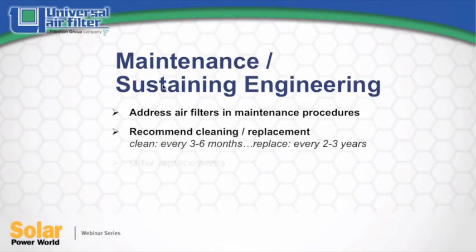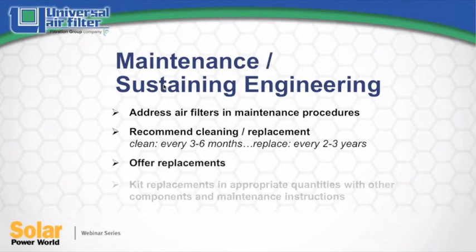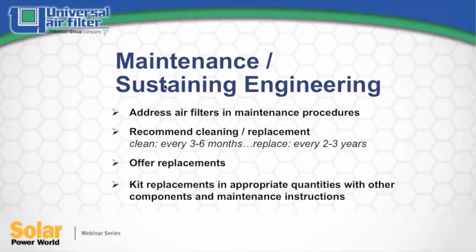The advice here is to have an air filter maintenance plan. Do not let dirt build up on filters and cut off cooling air, as we showed in the dirty filter photos earlier in this presentation. Make sure you and your customers have access to replacement filters, and recommend cleaning or replacement every 3 to 6 months.